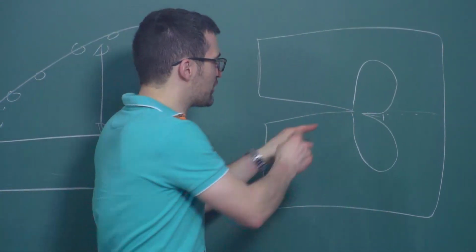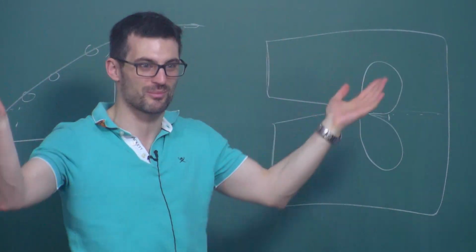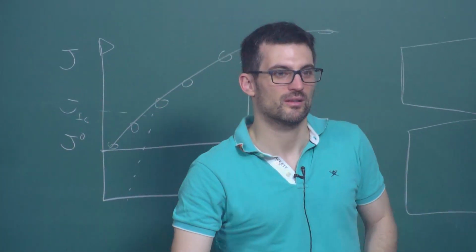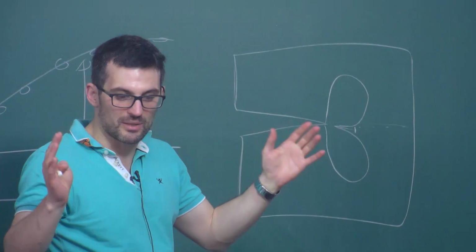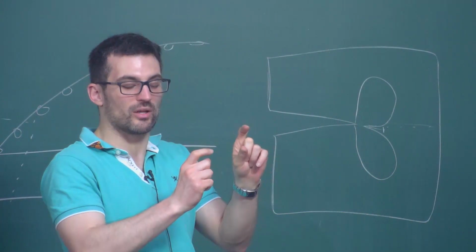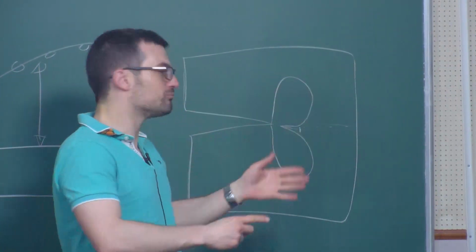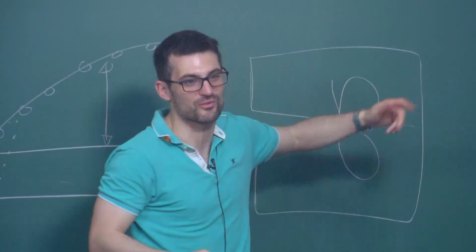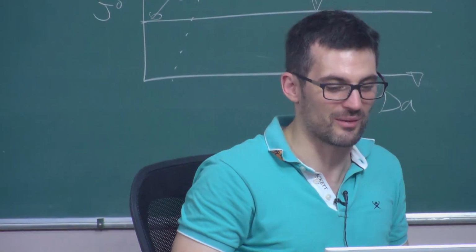I'm not measuring the plastic zone per se. It's just a ratio of some sort of plastic length measurement. That's the length scale that's going into gradient plasticity. Yeah, so the length scale going into my gradient plasticity is a material property that tells me how, in the presence of gradients, how much hardening happens in that material. But it is true that whether the effect is big or not is relative to the plastic zone and the gradients of plastic strain, which scale with this, of course. So I guess it's more or less an indication of the number. Yeah.